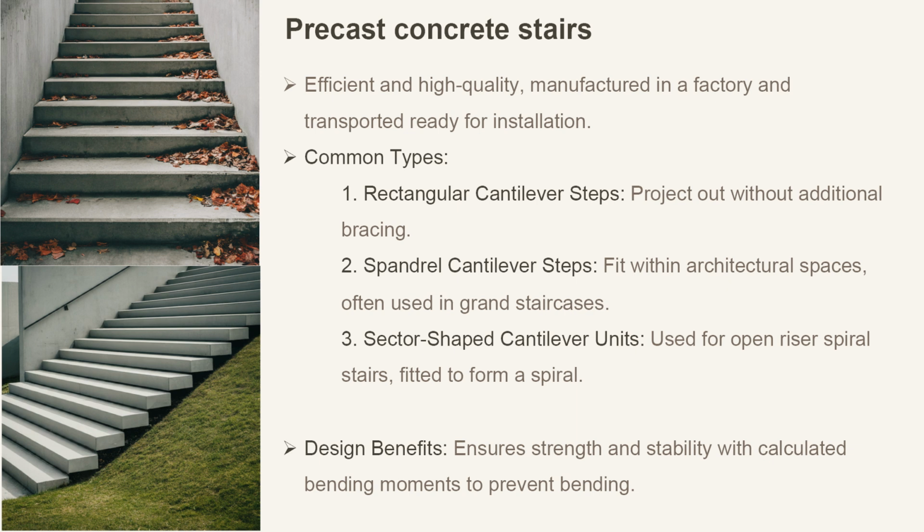Yes, now precast concrete stairs. They are widely used today for the efficiency and quality, as they are manufactured in a factory and then transported to the construction site ready for installation. There are three common types: rectangular cantilever steps, which project out without additional bracing; spandrel cantilever steps, which fit seamlessly within the architectural space and are often seen in grand staircases; and sector shaped cantilevered units, used for creating open rise spiral stairs fitted together to form a spiral.